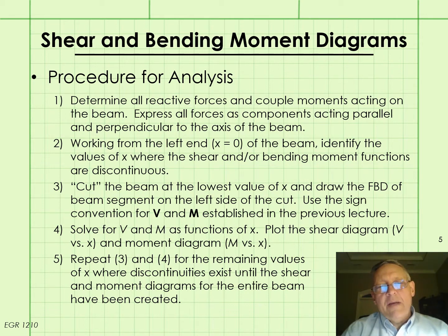For the second step, we'll work from the left end of the beam, where we'll set X equal to 0, and we'll identify any values of X where the shear and/or bending moment functions are discontinuous. Now remember, on the previous slide we identified these discontinuities as where a distributed load changes value, or where a concentrated force is applied, or where a moment is applied.